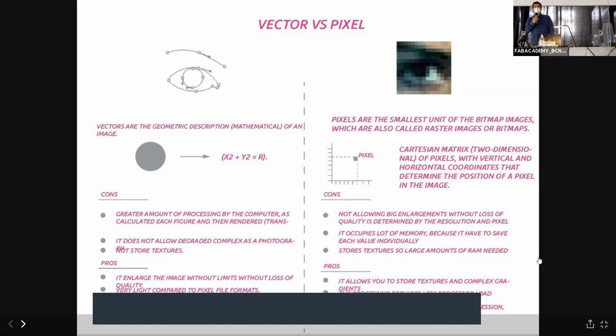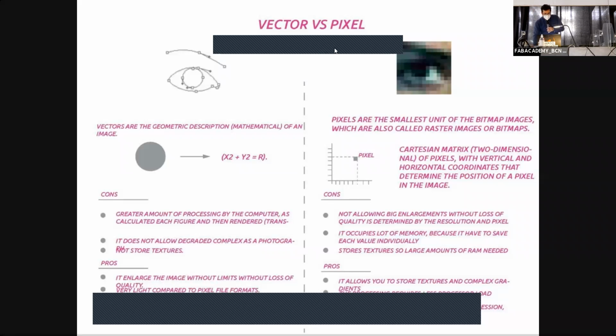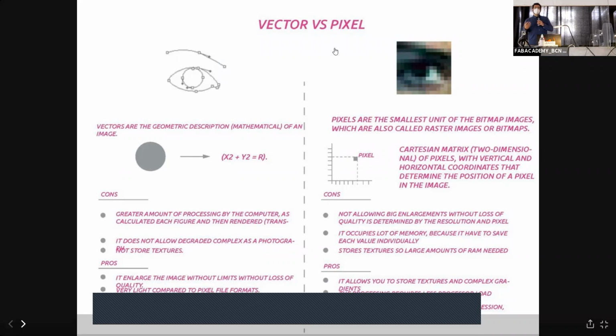So when you draw a circle, you actually put a line of code in the program that is the definition of the circle. That circle doesn't exist per se. What it has are properties. For example, we can set up a line weight, that is actually the thickness that we are visualizing for that circle. Or if the circle has a hatch, this one is a solid hatch. This solid hatch is not drawn in the file. What is done is visualized for you.